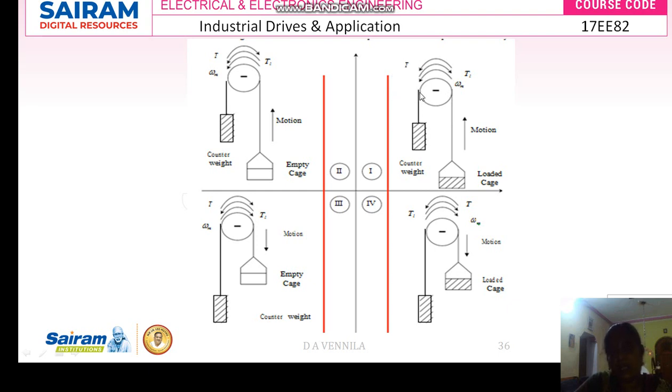be clockwise direction, but your load torque will be, sorry, here in this first quadrant operation, your speed and your motor torque will be anti-clockwise direction, and your load torque will be clockwise direction. I will show the operations.